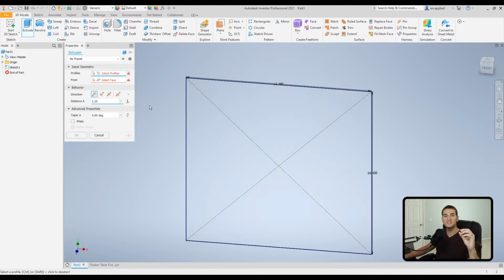So if you want to select a particular profile, you want to make sure you're within the sketch profile selector, and you'll know whether or not you're in it if you have this little blue line at the bottom. So we currently see the little blue line. If you click it again and it shuts off, you'll notice we can't pick up a profile. If that happens, don't worry, just go back to your selection filter area, click on that.